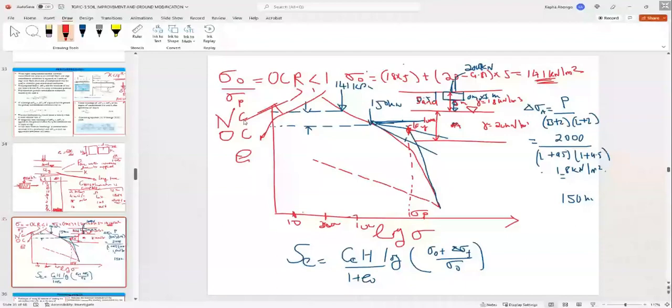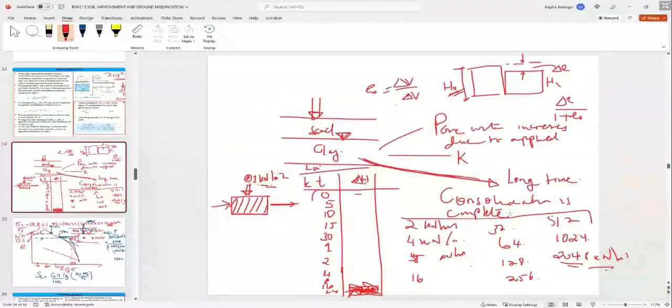How do you calculate the void ratio at 24 hours? Whitney is asking. You calculate from your dial gauge reading, changing height, time at 24 hours. That's the original height, and then at 24 hours this height, that much will be the void ratio.